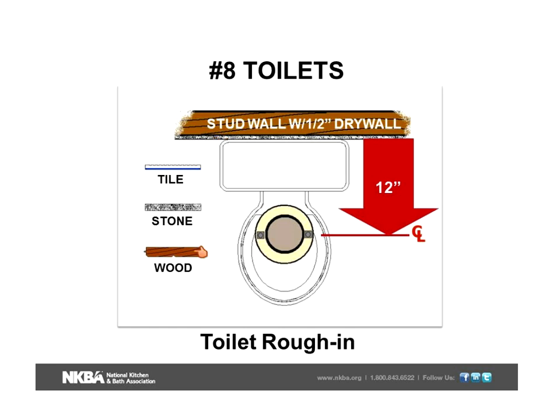And stone might be a little thicker than the tile, and a wood beaded board might even be more than that. So all of a sudden, that toilet will not fit. Now, I've seen lots of times where the plumber puts it in, you're standing there hoping it'll fit, and it did, and you think, thank goodness. And the plumber said, yeah, but the lid's not going to go on because the lid overhangs the tank.